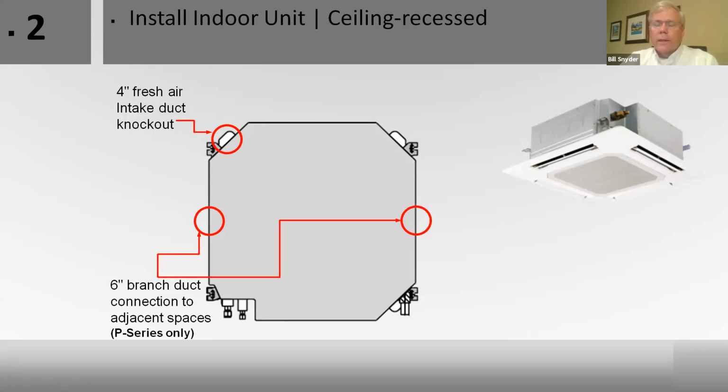It was leaking condensation. He got there, and the top left-hand corner was just hanging away, and it was enough to just tilt that unit enough that it didn't drain. So ceiling suspended units, same thing. You want to make sure these are anchored really well.